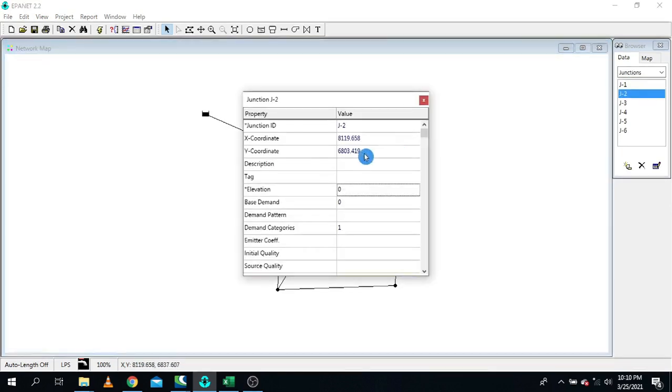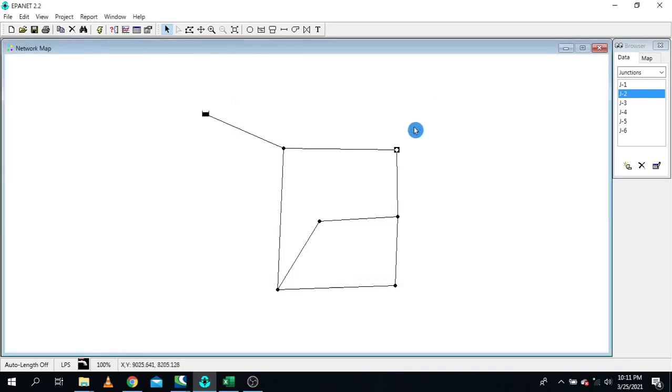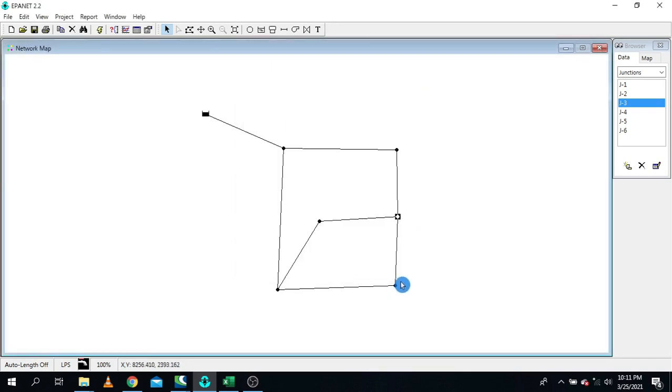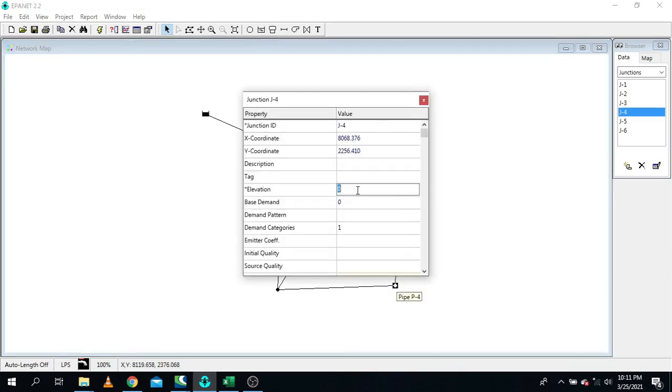And node B, elevation is 9.4. Then click OK. Node C, 19.2 as elevation. And again, node D, 25.2 as elevation. And again here, node F, if I'm not mistaken, node F, 5.5 elevation. And again, this one here, elevation is 2.1. So we assign here 2.1, then done.